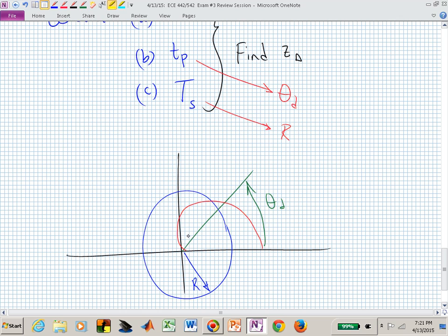I want it to be peak time less than, so I'm there. I want it to be percent overshoot less than, so now I'm in that little, I don't know what shape that is, but I've shaded it. Did I shade the correct shape? For percent overshoot less than, determined by that red heart or logarithmic spiral, and a time to peak less than whatever that angle produced. Yes.